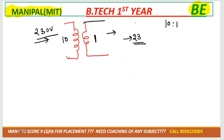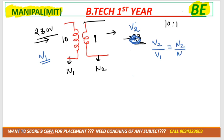See how it will work. This is primary turns, that is denoted by N1. This is secondary turns, that is denoted by N2. This is primary voltage, that is denoted by V1. And secondary voltage, suppose we need to calculate. So we'll have a particular formula for that. What was that formula? V2 by V1 is equal to N2 by N1.